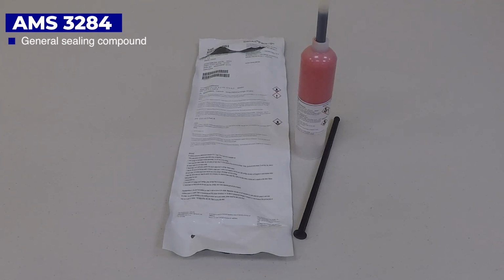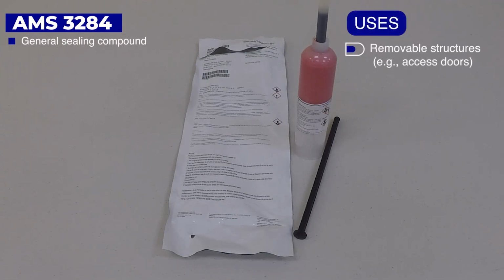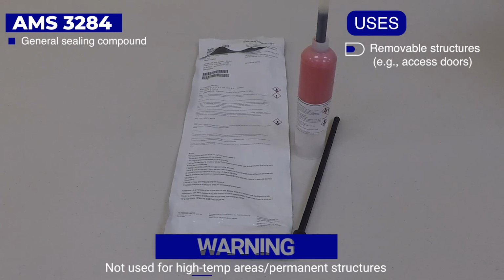AMS-3284 is a type of sealing compound used for sealing removable structures such as access doors, floor panels, removable panels, and fuel tank inspection plates. It is not used for high temperature areas or permanent structures. Type 1, no corrosion inhibitors. Type 2, non-chromated corrosion inhibitors, resists fuel and aviation gas.